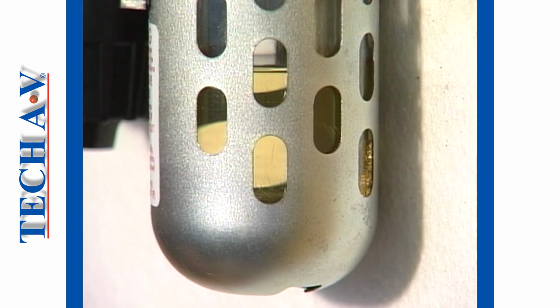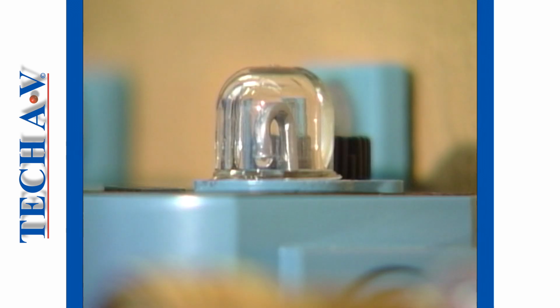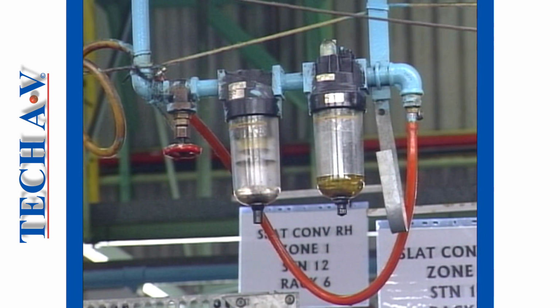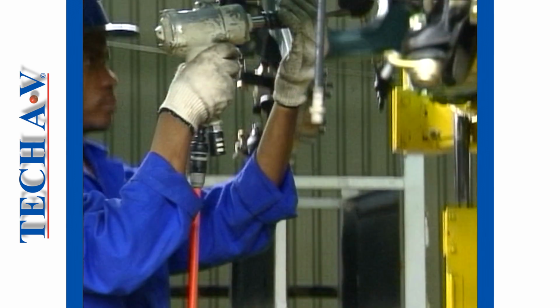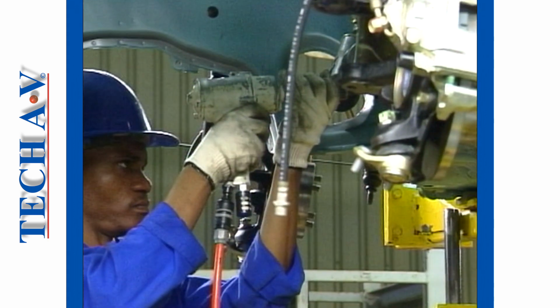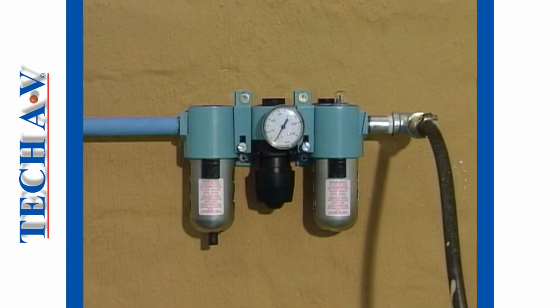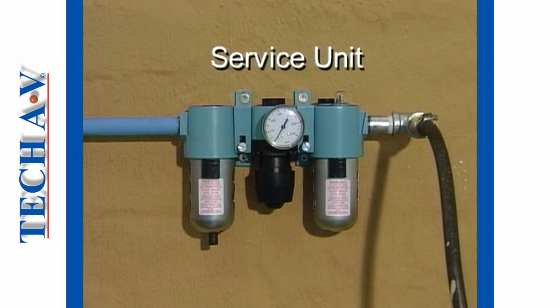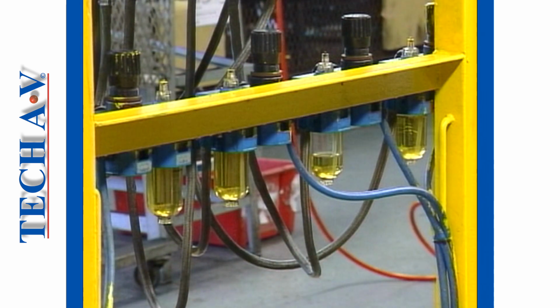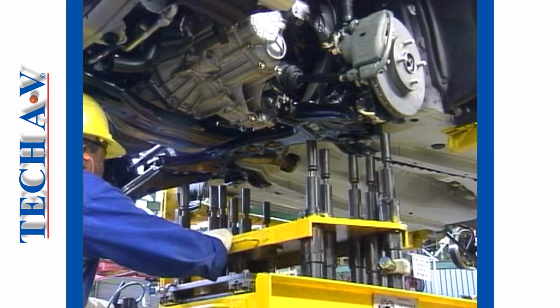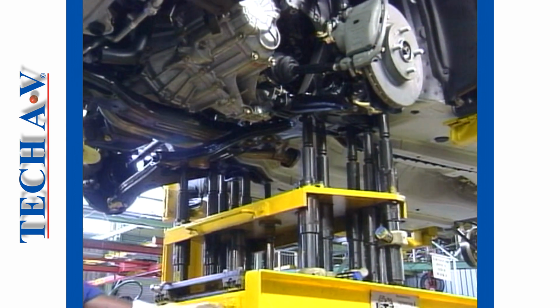Lubricators provide a small but steady supply of lubricating oil into the airstream in order to lubricate motorized air tools and actuators. Lubricators are required only where the working device has to be lubricated. You would not need a lubricator on a general-purpose airline. When the three devices are all linked into one modular assembly, we call this an air service unit. In summary, the secondary treatment of compressed air is needed for the protection of the working units and the control of air supplied.